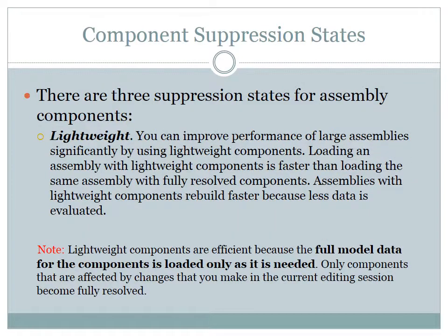The third compression state is lightweight. With this, you can improve performance of large assemblies significantly by using lightweight components. Loading an assembly with lightweight components is faster than loading the same assembly with fully resolved components. Assemblies with lightweight components rebuild faster because less data is evaluated. Lightweight components are efficient because the full model data for the components is loaded only as it is needed. Only components that are affected by changes that you make in the current editing session become fully resolved.